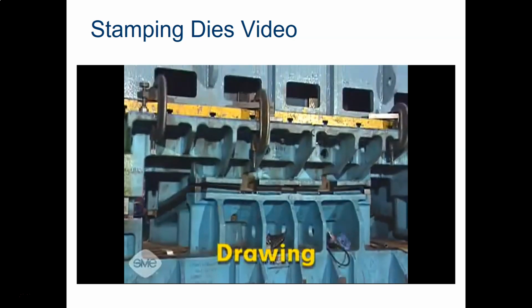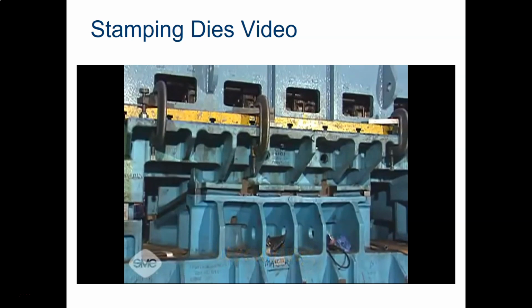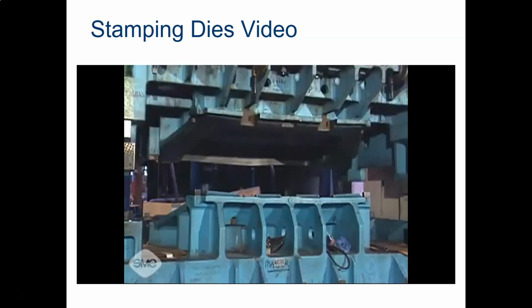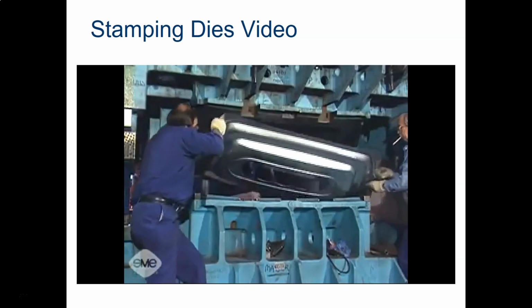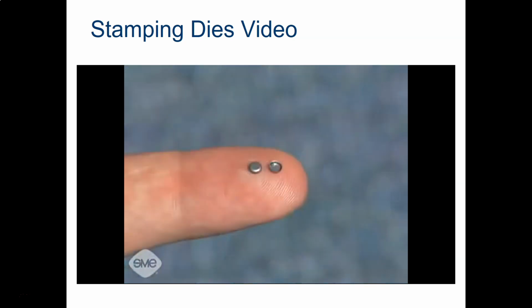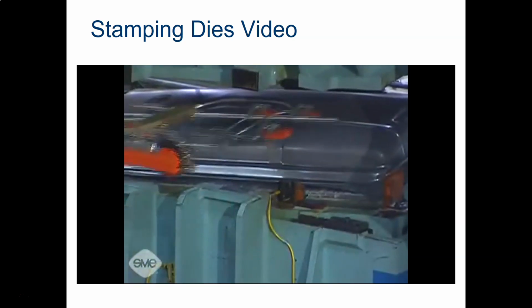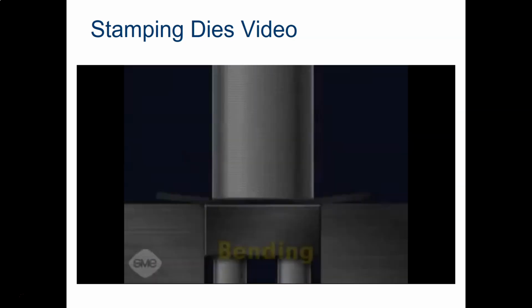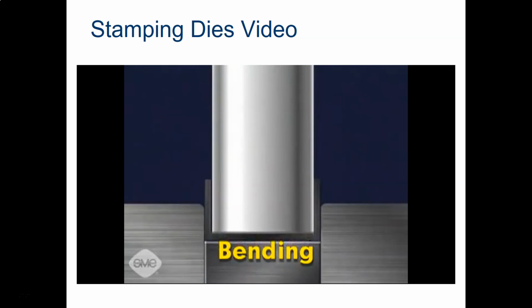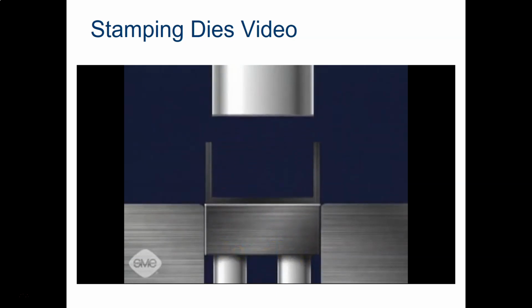Drawing shapes a flat pre-cut metal blank by forcing it into a die cavity with a punch without excessive wrinkling, thinning, or fracturing of the metal. Various complex forms may be produced by drawing. Drawn parts may vary in size from small parts up to aircraft and automotive parts large enough to require mechanical handling equipment. Bending is performed on sheet metal to gain rigidity and to produce a part of desired shape.